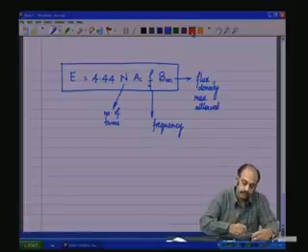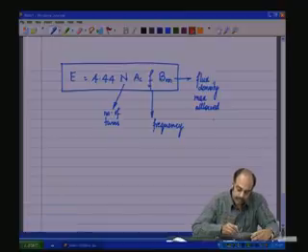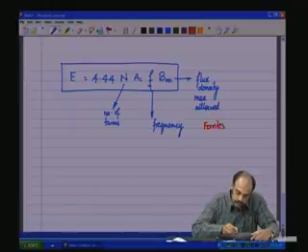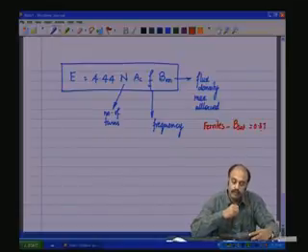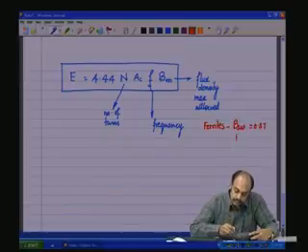Note here, for various materials, I can give the approximate figures. For ferrite materials, B sat is around 0.3 Tesla. So, Bm should be less than 0.3 Tesla, should be around 0.25 Tesla.